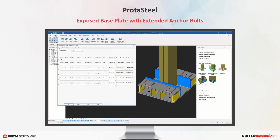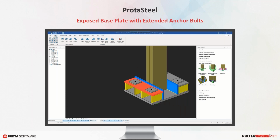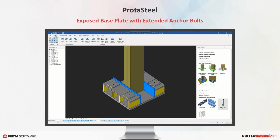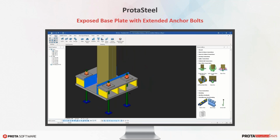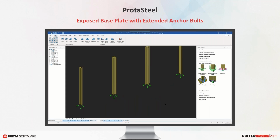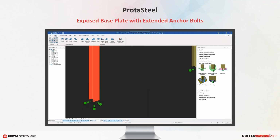This method aims at concentrating all plasticity in the extended region of the anchor bolts. Especially in the intense load scenarios, the traditional embedded base plate thickness may be unpractically high. In order to overcome this design issue, exposed base plates can be used to reduce base plate thicknesses.